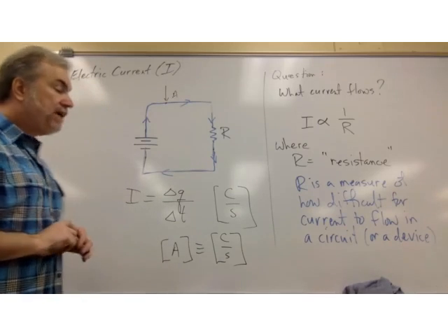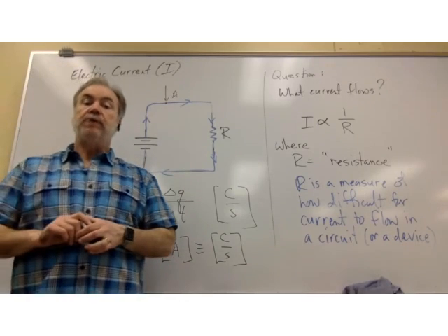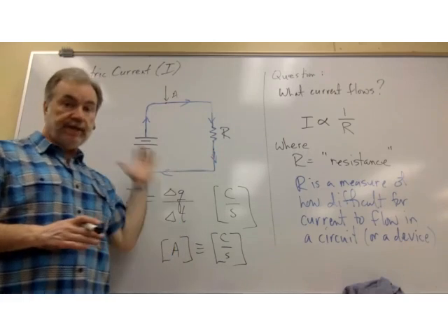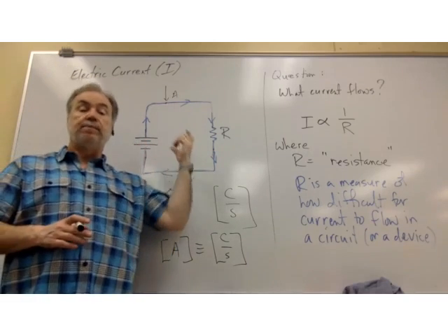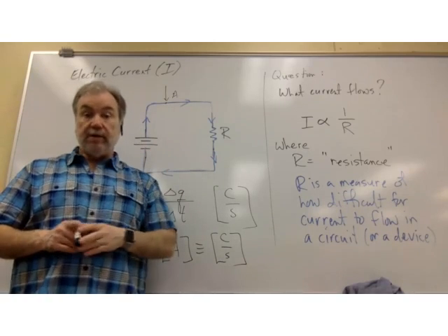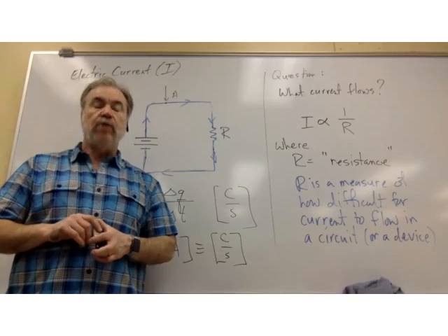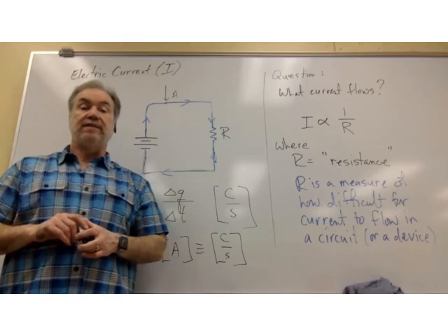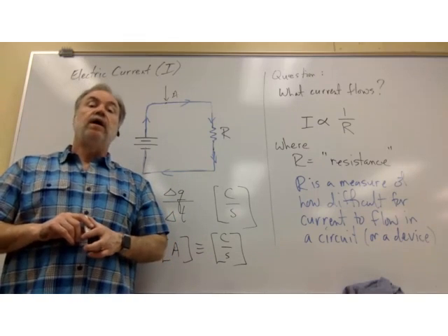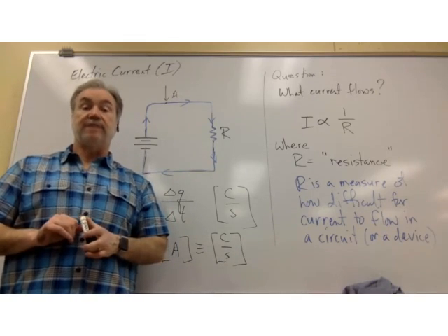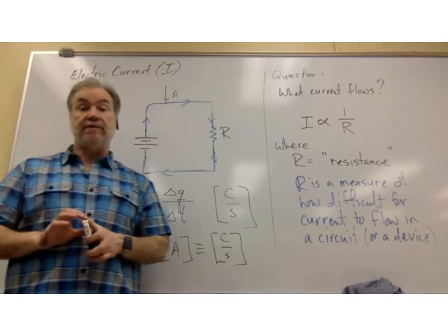So we want to make a distinction between the potential difference that the battery supplies to the whole circuit versus the potential difference that the battery was built to provide. The potential difference the battery was built and designed to provide is decreased somewhat by the effect of the internal resistance that the battery inevitably has.